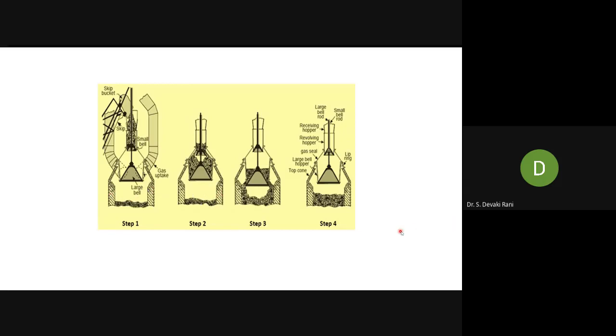Blast, hot air, is entering into the blast furnace at the tuyere level at such a high velocity, and it is staying in the furnace for a few seconds and is let off to the gas cleaning system, followed by the blast furnace stove to recover the potential heat.